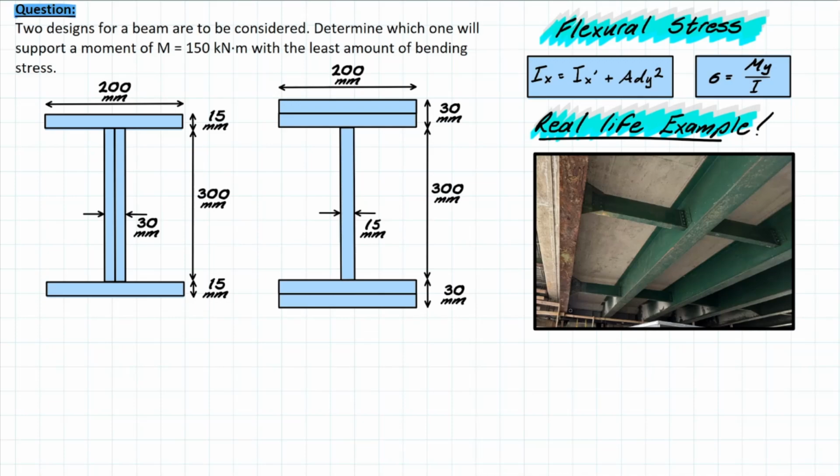So what we do sometimes, if this corrosion is super bad, is we can do something like this where we add steel plates in sections where we are losing area, supplementing that area with a new steel member in order to bring up that moment of inertia value based on an increase in area. And we know that the further away the area is from that central axis, the more we are greatly increasing the moment of inertia. But for now, let's just think about this problem and see what we're dealing with.